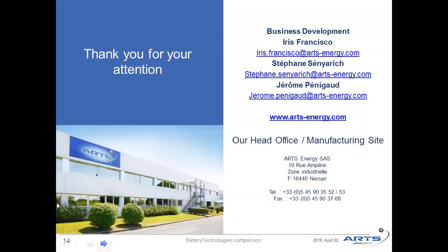So there is a question about BMS, battery management system, according to battery technology. I would say that the battery management system is mainly in relation with the way of detecting the end of charge. So for nickel metal hydride, when you speak about BMS, the key point is the choice of the end of charge detection, plus the state of charge. So we use a coulometer.